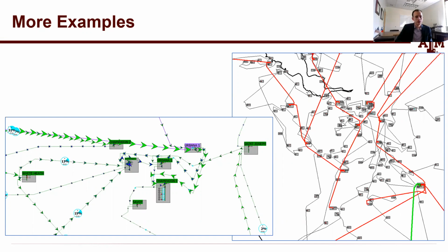The logic behind routing these in this way is that we already have a power system model, so we already know what the parameters of the lines are. I'm not looking at the route of a line and saying it's longer, therefore I'm going to give it different parameters. We know what the lines are, and the length on the diagram is not necessarily associated with its parameters.